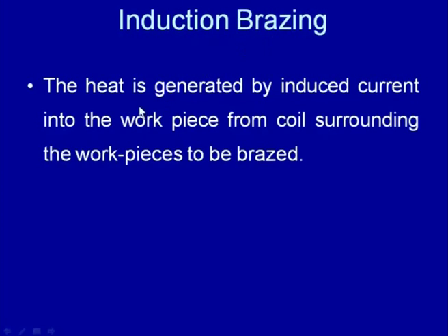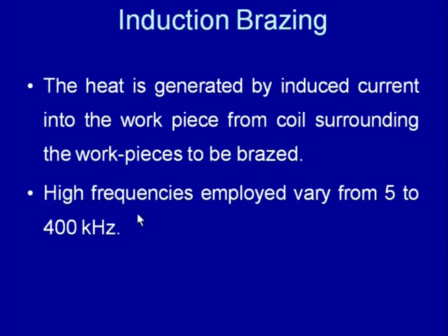In case of induction brazing, heat is generated by induced current into the workpiece, which is brought close to the coil which is surrounding the workpiece to be brazed. So, basically by the induction effect, the current is induced, and this induced current helps in electrical resistance heating of the component to be joined by the brazing, and especially the high frequency is used for developing the heat, and the frequency can vary from 5 to 400 kilohertz.